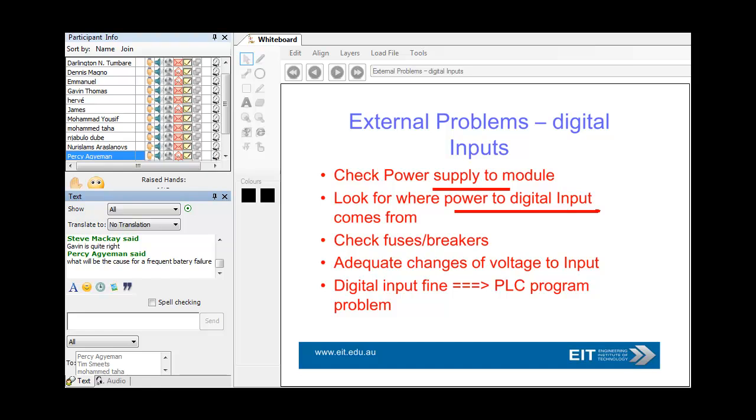Firstly, it was to do with batteries. Batteries were connected up on the plant, and they were connected up in series, so you had 48 volts. The modules of the PLC were sized for 48 volts, so there was no problem at all. But they weren't sized for 50 volts or above. So it was 48 volt modules, and the batteries, when they were fully charged, lead acid would actually go well beyond that. So the digital inputs were always failing, and they had thousands and thousands of inputs.